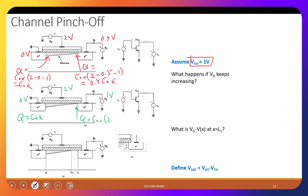What is the channel potential at this point? Can you say it's 1? And then the Vth is also 1, right? So this gives me 0. I don't have any charge on the right. And that is called pinch off.